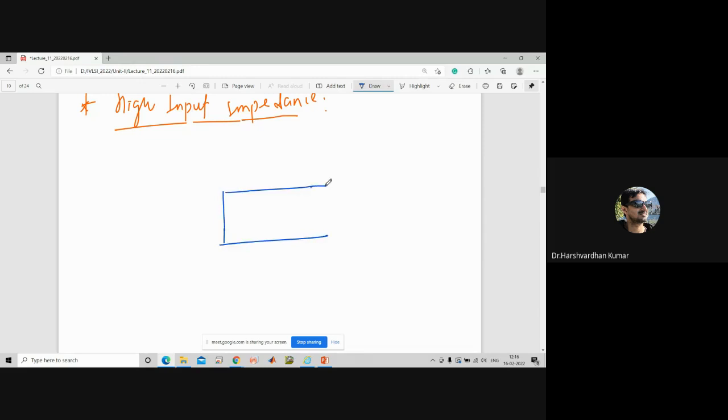Let us say this is N plus, this is source and this is drain, and here this material is the silicon dioxide, and here is a metallization, that is gate, right? This material is known as SiO2, that is insulator. This is the P-type substrate bulk material.